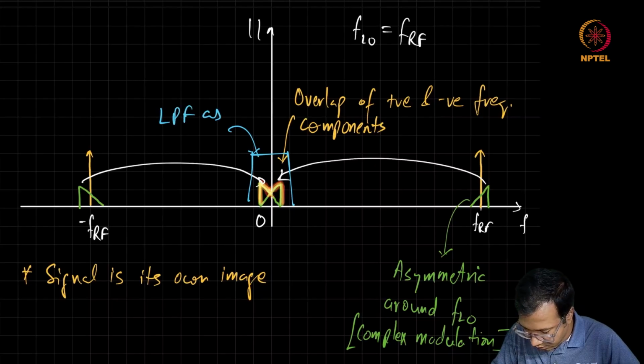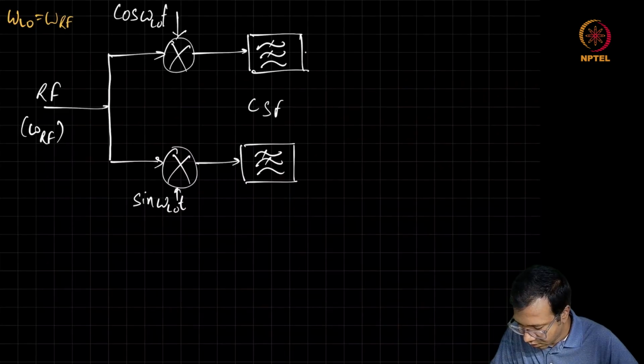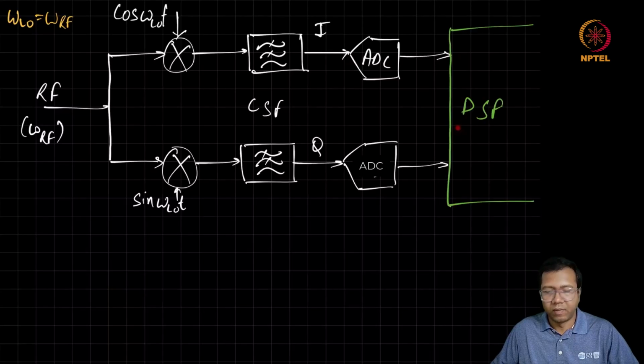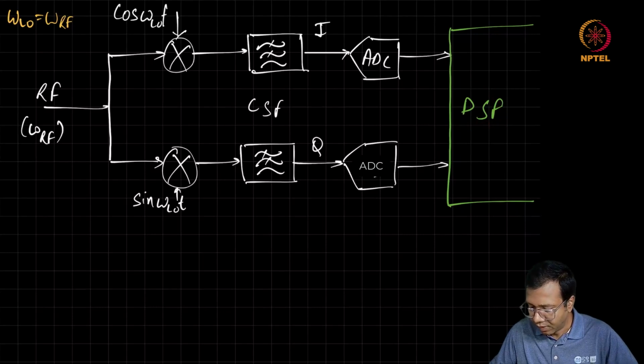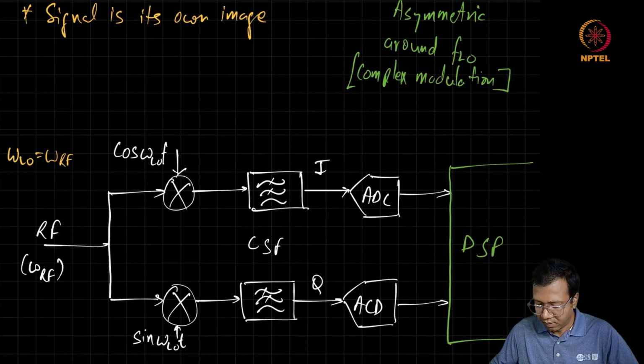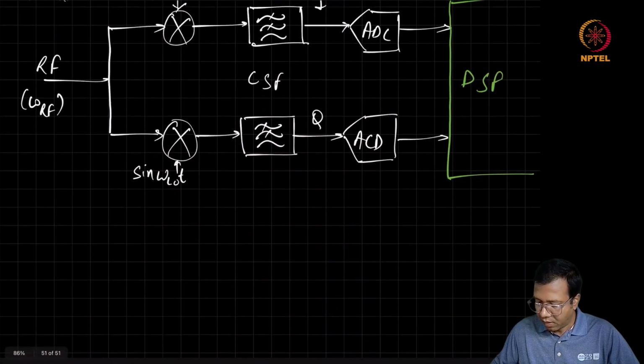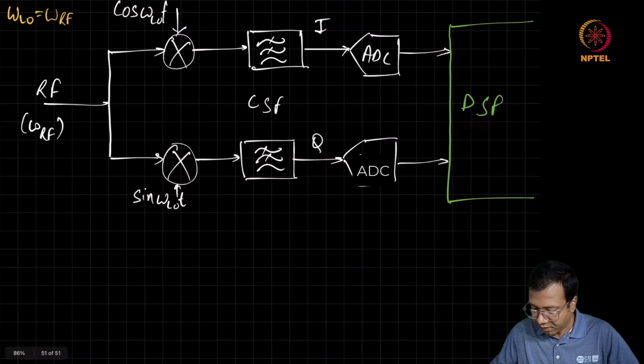These outputs, I and Q, which are right now around DC, can be digitized. As we have seen, we can add a 90-degree phase shift in the Q path and add the two signals so as to extract the signal component without losing the information. And I will just put all those operations as a part of a digital signal processing block.